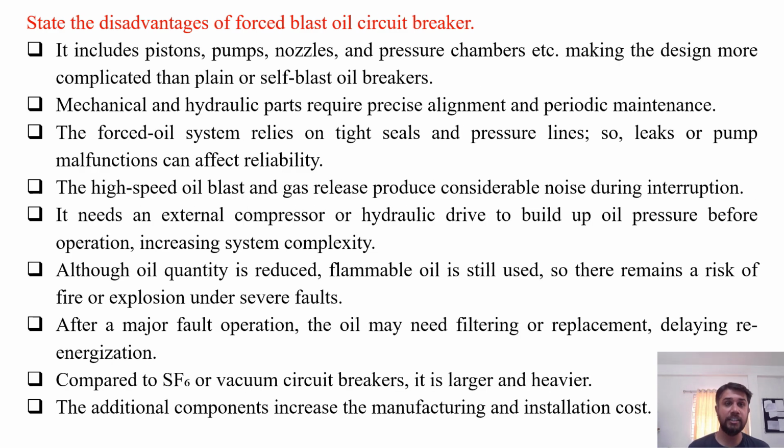State the disadvantages of forced blast oil circuit breaker. It includes pistons, pumps, nozzles and pressure chambers etc., making the design more complicated than the plain or self-blast type oil circuit breakers. Mechanical or hydraulic parts require precise alignment and periodic maintenance. The forced oil system relies on tight seals and pressure lines, so leaks or pump malfunctions can affect its reliability. The high-speed oil blast and gas release produce considerable noise during the interruption process.